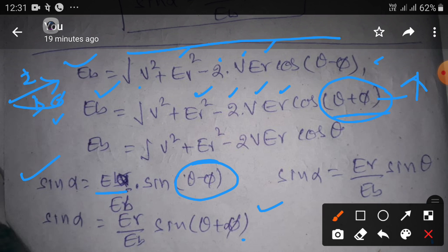Induction motors always draw lagging power factor. Then the power factor value may decrease to less than 0.85. But the discom has restrictions: it should be maintained at 0.85, otherwise there is a penalty of some lakhs of rupees.